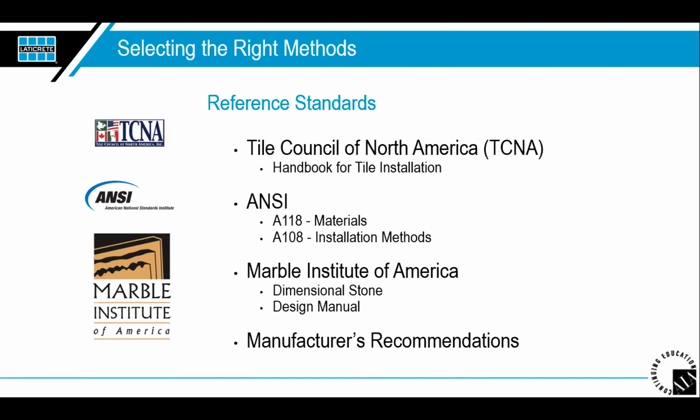The TCNA Handbook is one of the first things we'll call out. It's for ceramic tile installation, with information on industry guidelines and specific installation types. Then we have the American National Standards Institute, ANSI for short. It has information on installation and testing methods and product performance requirements, and it also establishes the minimum requirements for product performance.